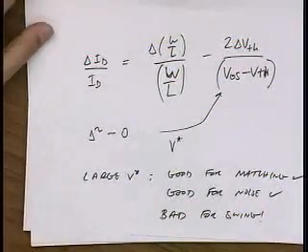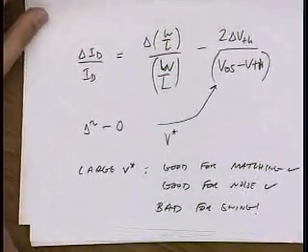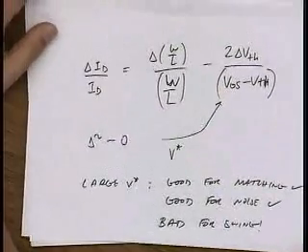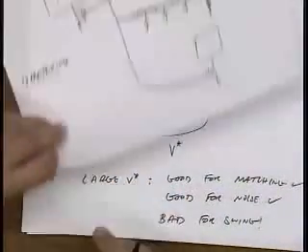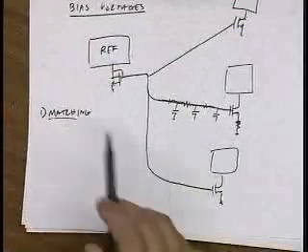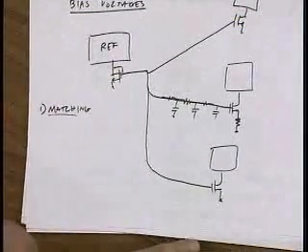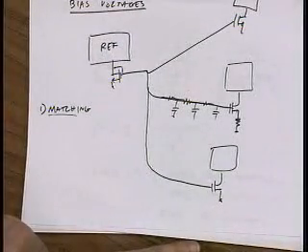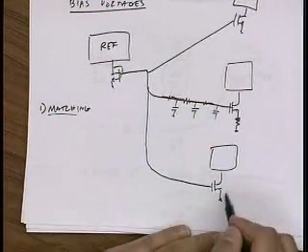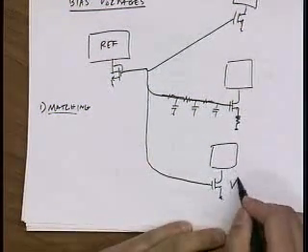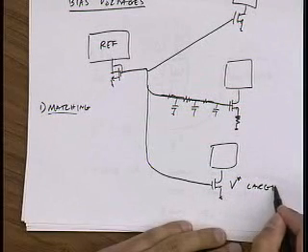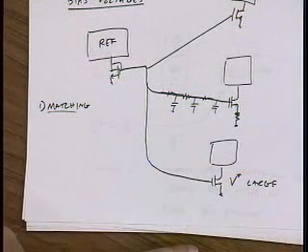So, in fact, this gives us a very nice recipe for routing currents and voltages, because if I come back here, if these transistors are really far away from each other, I can still do this as long as I use a large V star to reject the threshold voltage variations. Okay?